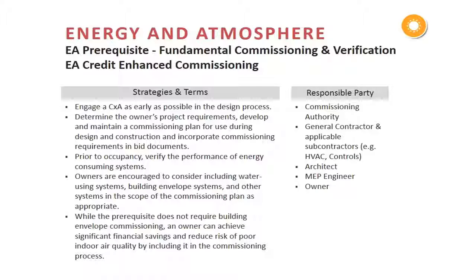Now there's a lot of equipment that's required by LEED to be included in commissioning, really any energy using systems. But there's also the opportunity to include some of those other types of systems. While they may not be mandatory, there's still tremendous benefit by including them in a quality control process like commissioning. And then building envelope commissioning itself is not mandatory, so it's not included at the prerequisite. But not only do you get a couple of points for including it, there's also tremendous energy performance value to the owner throughout the life of the building if they know that their envelope is operating properly.